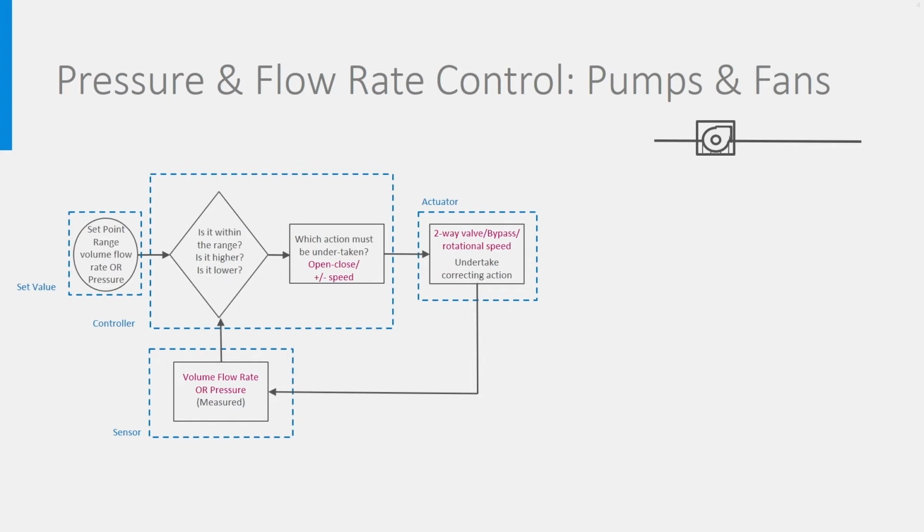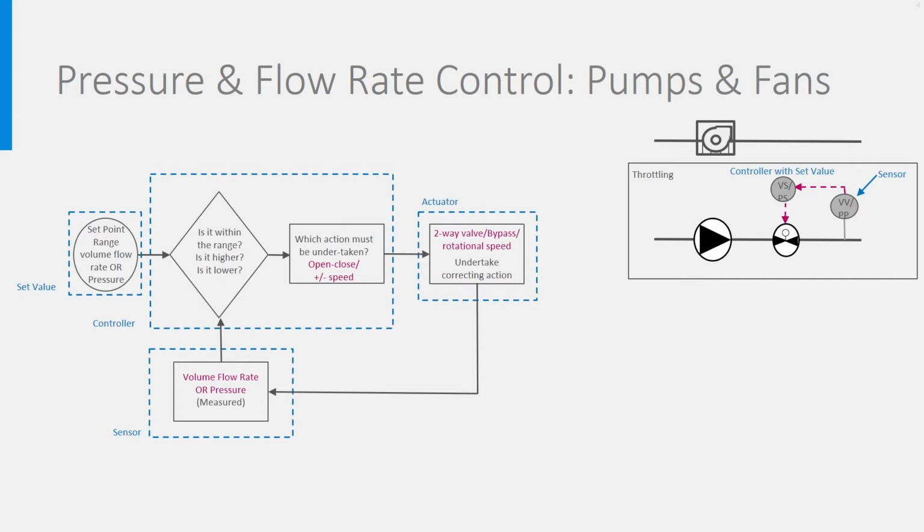However, sometimes we really need a pump or a fan to overcome high static pressures resulting from the natural decrease of flow velocity, referred to as dynamic pressure, due to the flow losing kinetic energy because of friction along the pipe's wall. Pumps and fans add this missing kinetic energy to the flow by adding pressure on it. They push the fluid up, let's say. The picture above shows an air duct with a fan. The second one, a water duct with a pump. We'll explain the working on the second one. It is exactly the same with a fan.